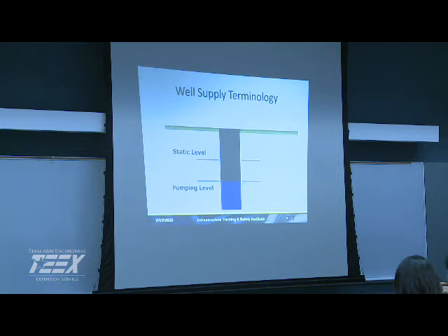That's part of the process. I mean, it's good to have an artesian, because that means you're not using a lot of electricity to get the water out of the ground, because it's up there real close. And is it at certain times of the year that it flows like that, or is it constant? It's constant. It's interesting, because normally with artesians, again, you have to go and look at your hydraulics to see where your aquifer actually flows to. But if you're on the low end of the aquifer, you're going to have a lot of hydraulic pressure, and sometimes it'll fluctuate throughout the year.